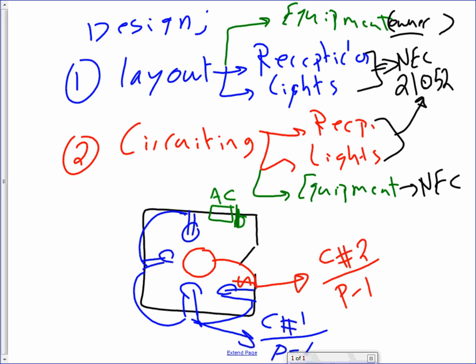In most buildings, they would have multiple panels. In the apartment building that we have, we're going to have one panel in every apartment. So apartment 1 will be P1, P2, P3, P4, and P5 is for common loads between all the panels. You need to identify where this circuit is going. Is it going to panel 1 or 2 or 3 or 4? If you have only one panel in the house, do you need to identify the panel? No, it will be redundant.